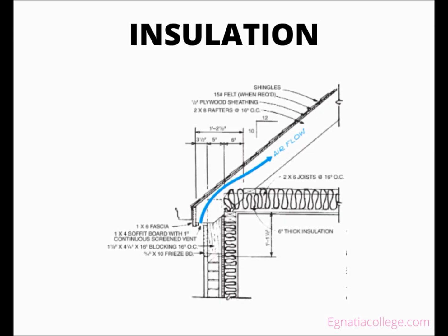For example, if bats are to be used in a 2x4 wall, the insulation will be indicated as 3.5 inches thick, the width of a 2x4. One of the main reasons many houses are framed with 2x6 is to increase the space for insulation between the studs. Where insulation is used in ventilated spaces, there should be room for the necessary air circulation.